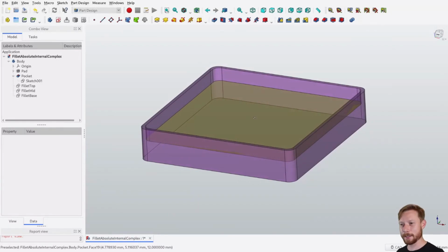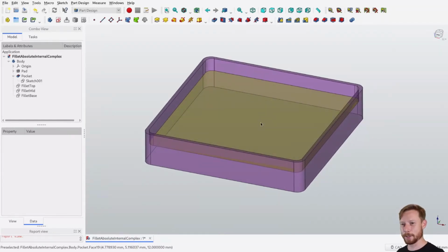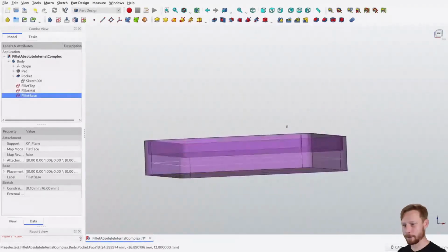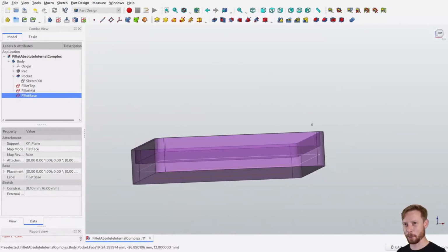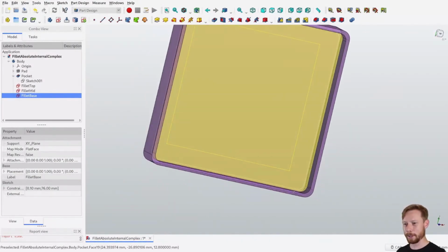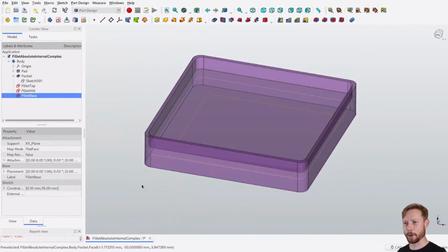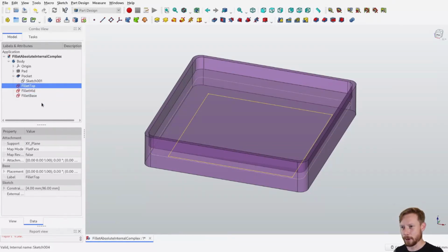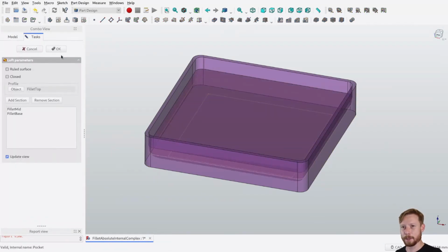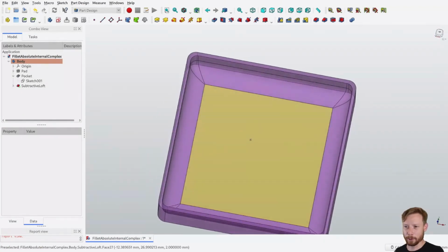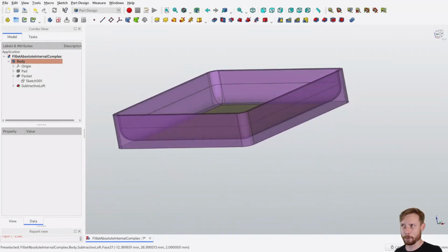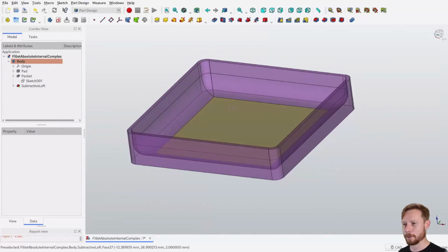I've done this using 3 sketches, a subtractive loft. So the bottom one is the endpoint for the fillet, and the middle one is a guide. The top one is just exactly the same geometry as the base. So if I select all of these, and then I do a subtractive loft, we now have a 10mm fillet on an object with 3mm corner, 4mm corners.